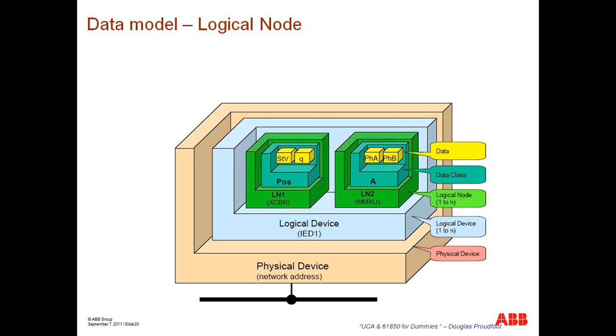Moreover, there are also available on the market electronic pieces of equipment or I/O boxes. In our case we have a solution called the RTU 560, which can actually be hardwired to a primary apparatus and then model that particular piece of equipment in 61850. So whether it's a breaker, transformer, and so on, that could be performed. So even if you have a device that did not come from the factory with this electronics interface, there are options available to do that in the market from ABB.